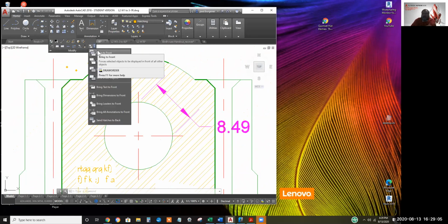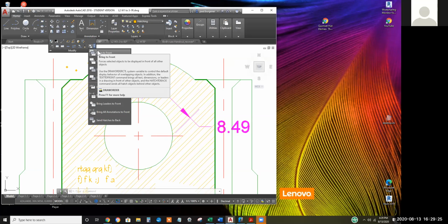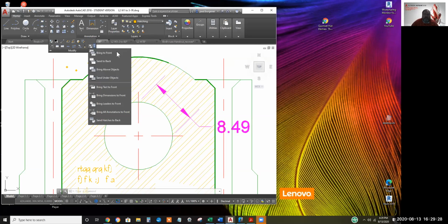When you get into the solid fill crosshatch pattern, be ready to use this draw order, because let's say you put the electric lines over the tennis court and then you go to solid fill. Anyway, generally you want your solid fill to be in the back, your dimensions and notes to be in the front. That's key. DR enter is a quick type in. Good info. Yeah, these down here I never noticed before. They may have come in a recent release. And I remember these for many releases.